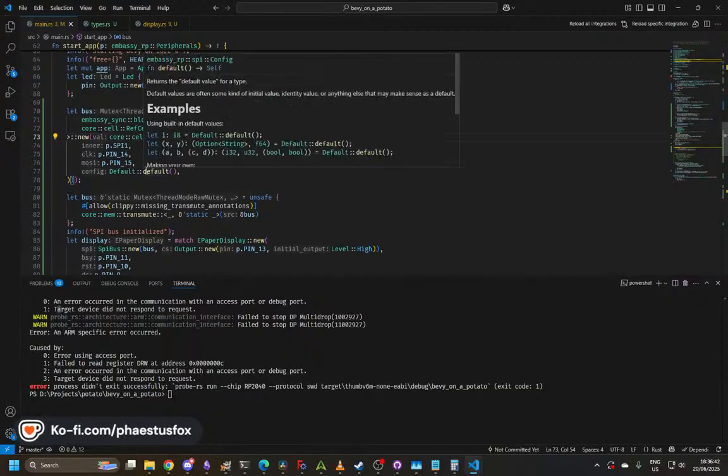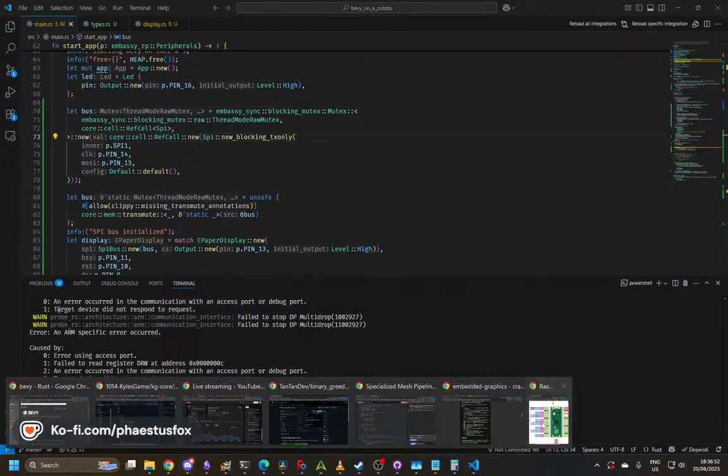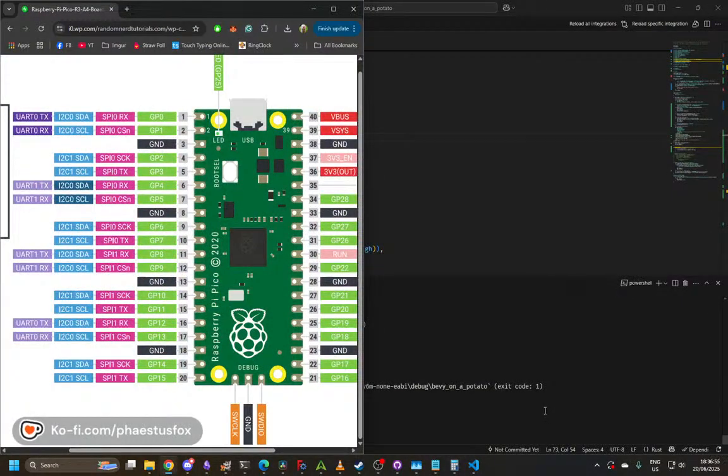Yep. My normal mistake I make with this is I always get the clock and the data thing backwards. But I'm 90% sure I checked this. Your TX is 15, and I'm currently touching it. Yep. And then if we touch clock, clock's not... Yeah, the clock is the next pin up. And we go, no, that's interesting. No, clock's definitely working.